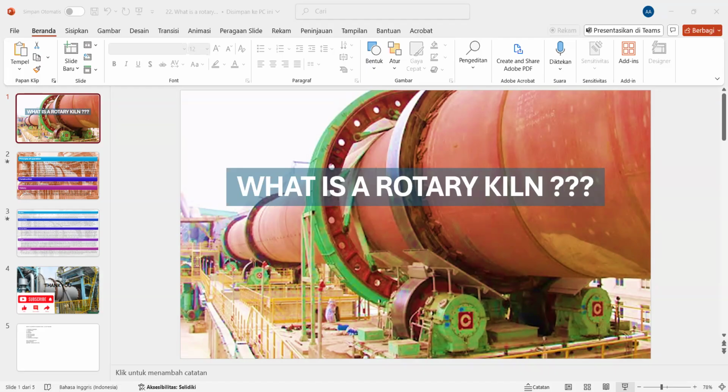Principle of operation. The kiln is a cylindrical vessel inclined slightly from the horizontal, which is rotated slowly about a longitudinal axis. The process feedstock is fed into the upper end of the cylinder. As the kiln rotates, material gradually moves down toward the lower end and may undergo a certain amount of stirring and mixing. Hot gases pass along the kiln, sometimes in the same direction as the process material, but usually in the opposite direction, counter current.